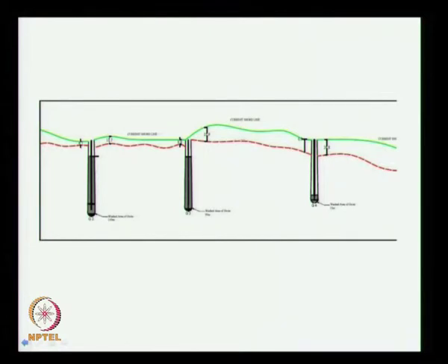This is what we predicted, about 20 meter will get eroded as we start constructing our groins. So this figure is clear, this is the shoreline in December 2011 when we started the construction of breakwater and construction of groins. Over a period of time the erosion has taken place like this. Now we are doing the artificial nourishment and bringing this shoreline green line to this level, tip of the groin.